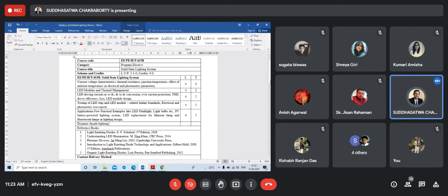Just like a conventional diode, there is a barrier potential, which depends upon the different types of doping materials. So here also the barrier potentials will be there. Accordingly, the voltage we control and the current flowing through the LED should also be controlled by using the resistance only. That is the simplest form of driving circuit.